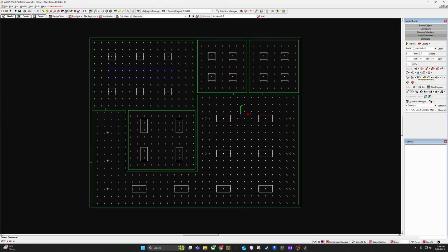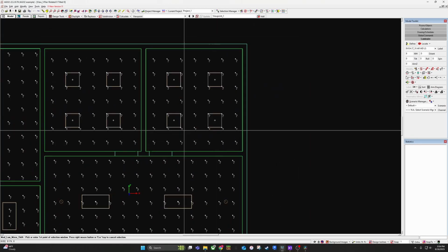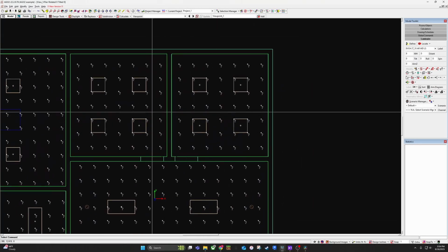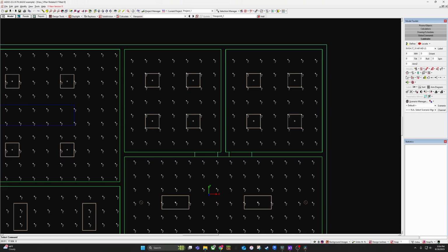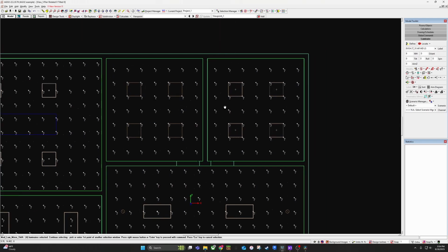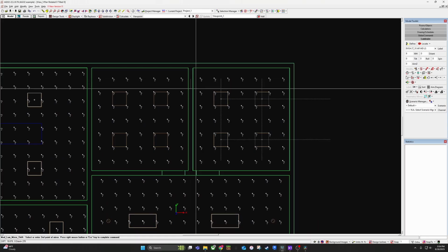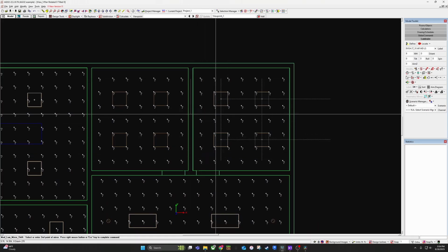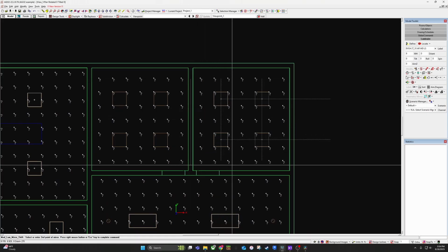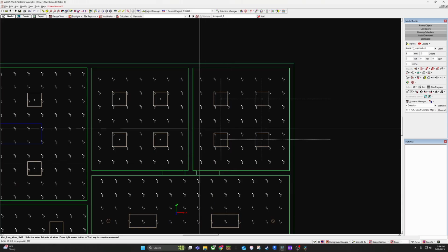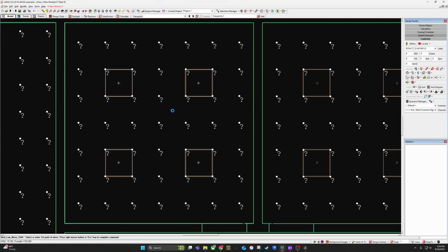What else can I show? You want to mirror lights? I think a good use of mirroring lights would have been here. So if you want to mirror, let's choose window. Right click to enter the command. Choose a plane that you want to mirror off of. So here I'll go in the middle of these two walls, or this one wall. Perfect. Then now they're all here.